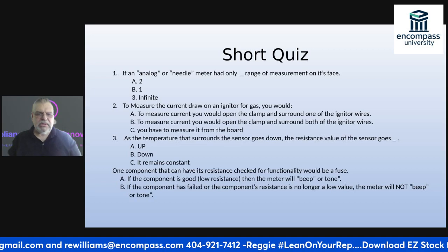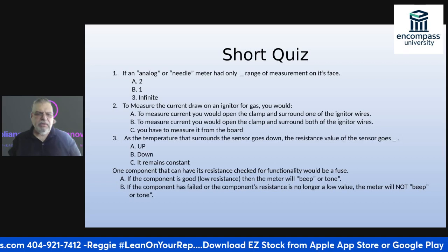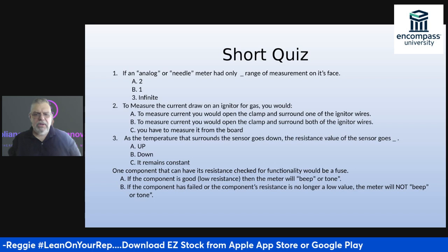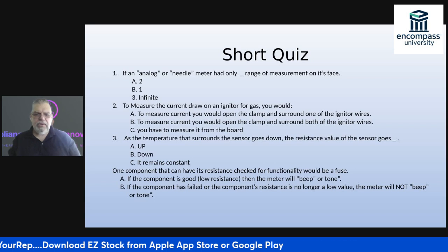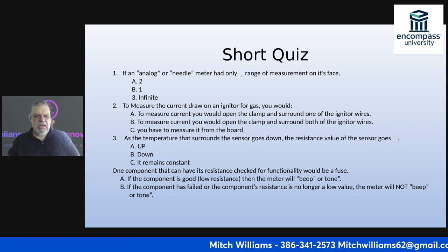One of the components that can have resistance checked for its fixed functionality would be a fuse. If the component is good, if I have low resistance, then the meter would beep or give me a tone. Like I said, mine gives me a tone, it's not a beep.